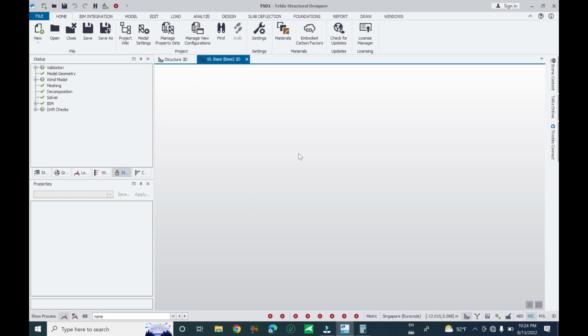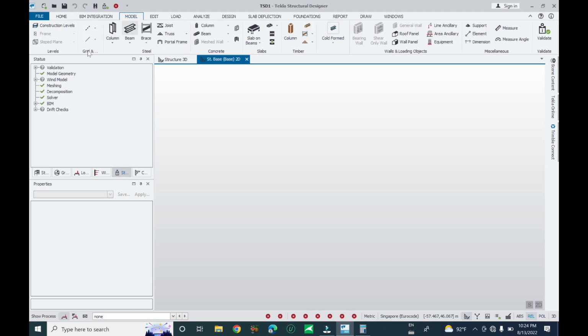To create a structural model, you have to create grid or construction wall. You have to insert the wall from one floor to another and create a construction line or use the rectangular wizard. This one is in the item of grid. In this case you can use a construction line or parallel line or perpendicular line. It can help you to draw other objects on the grid line. Now let's start by clicking construction wall.